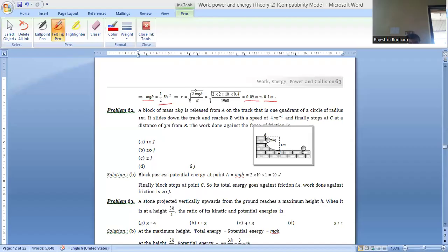So here we write power equal to force into velocity. Force means resistive force plus accelerating force, into velocity. Resistive force is given, 750 Newton. So (750 plus ma) into 30 equals power, 30 into 10^3. 30 cancels on both sides. So 10^3, 1000 minus 750 means a equal to 250 by 1250, which is 0.2 meter per second square.